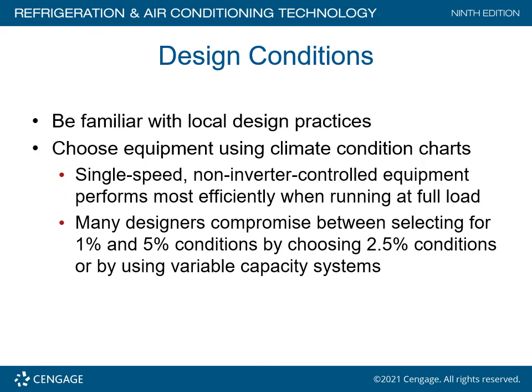Very seldom do I ever have to replace parts on a mini split because they're so well designed. As far as the motor, the ECM motor versus the constant run type motor, these motors ramp up, ramp down based on the actual need at that given time.